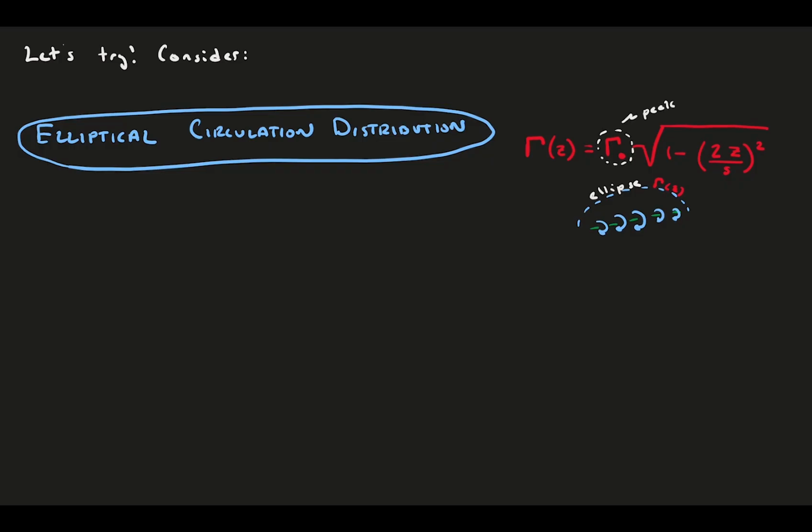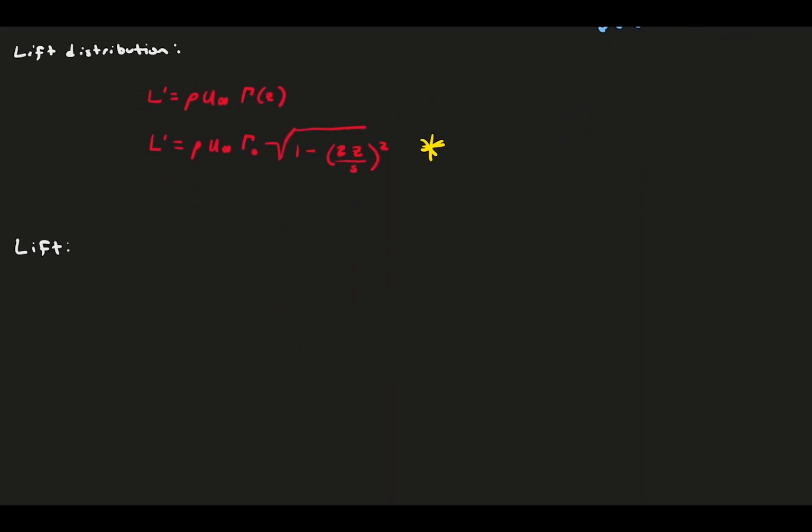Straight away, we can calculate the lift distribution, L prime. To calculate the total lift, we will have to work a bit harder. Write out the equation with the integral. Here, we're going to deploy a tool we used in thin airfoil theory.